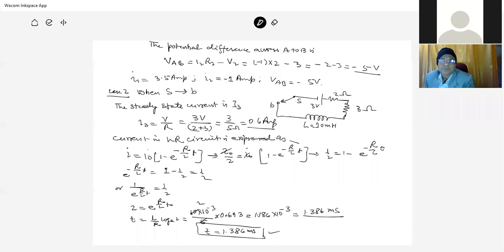And if you want to calculate the potential, multiply the impedance with the current. Then the second part is sometimes also called the extra part that we have to calculate. Here in the circuit, we have included capacitance as well as inductance. The capacitance part, as it is DC, is not applicable here, so that part is deleted.